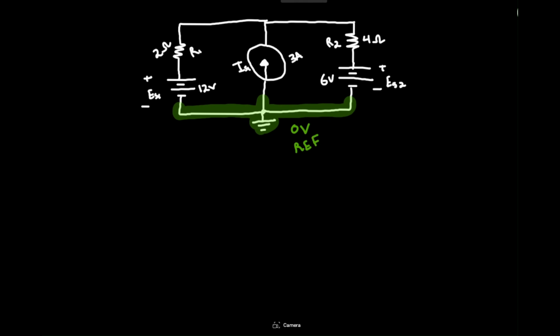Now the voltage node is going to be this one. Since it's easier to visualize, it's connected to all these 3 branches, and these 3 branches have currents going through them. Now to identify the currents, we're going to label them. We can assume for branch 1 that the current is leaving. When it's leaving, we know it's positive. That's the second thing you gotta keep in mind. The currents leaving the node is positive, currents entering the node is negative.